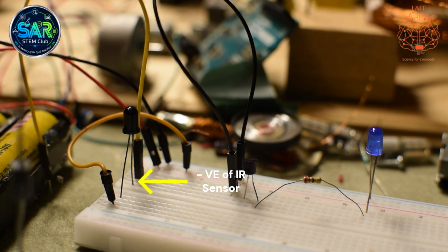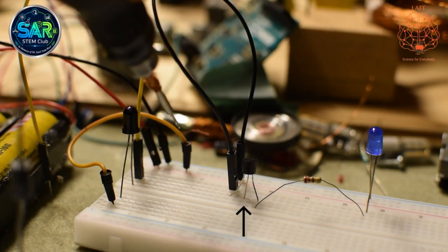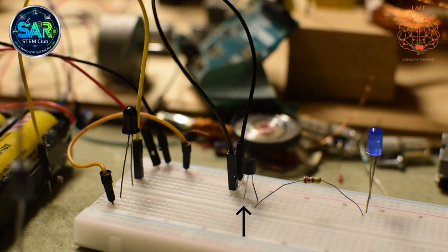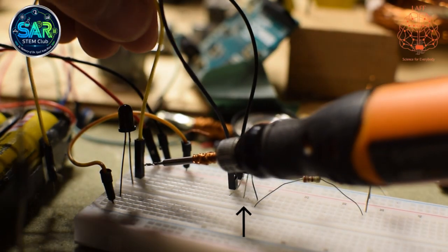Now we are going to connect the negative of the IR sensor through this yellow wire with the base of the transistor. Here you can see this is the negative side of the IR sensor. Now I am connecting it with the base of the transistor.